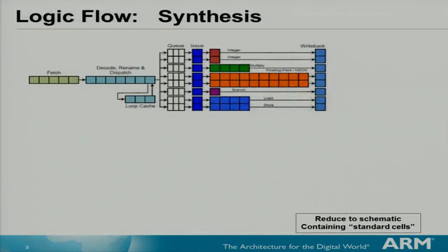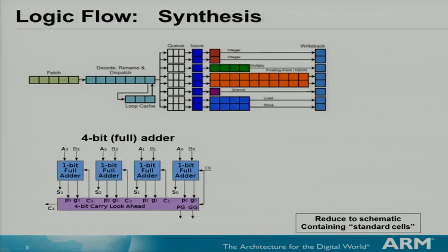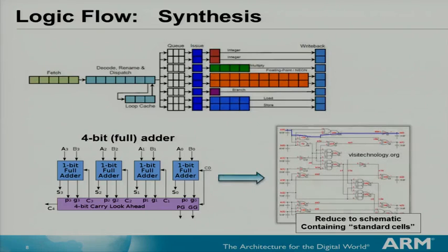So very briefly, what SPNR does is, we have a piece of design architecture. We identify, say, one part, and the synthesis tool will create a netlist or a circuit based on what are known as standard cells. So here, I'm showing a very common component, a 4-bit full adder. And what the synthesis tool does is, based on the design constraints that are given for timing, area, power, it will try to identify the best circuit components from your standard cell library and put them together. And here, this is basically the circuit netlist. And you can see the main gates involved here that's shown through the lines here.